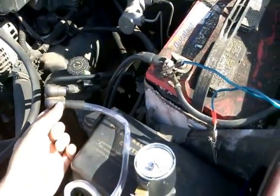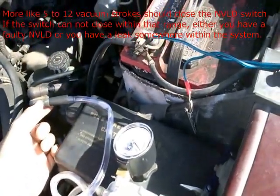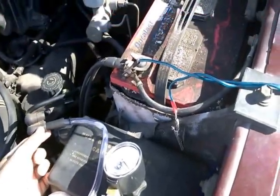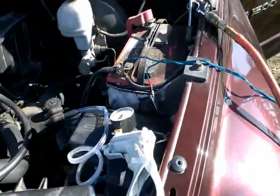Then you apply at least 3 to 5 strokes, and that should create about an inch of H2O. By applying that 1 inch of H2O, the natural vacuum leak detector switch should go from open to closed.